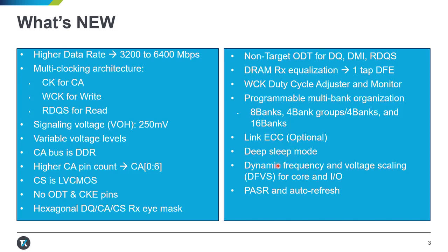We have a few power saving features like deep sleep mode and DVFS-C and DVFS-Q, which is dynamic frequency and voltage scaling. And we also have auto refresh and PASR, which is partial array self-refresh.